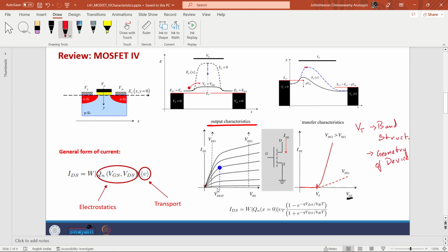Do you understand? This is the ohmic region. This is the saturation region. These are the different values of VG. VG is increasing as I go in this direction. VDS is increasing in this direction. As I move up, VG is increasing, and VT is occurring somewhere over here. Now, what happens because of DIBL?